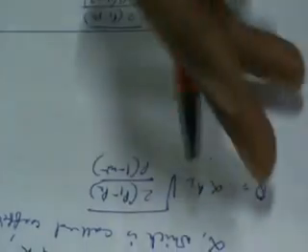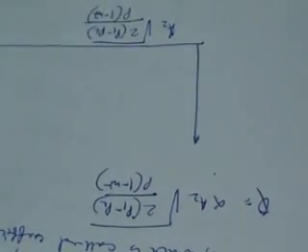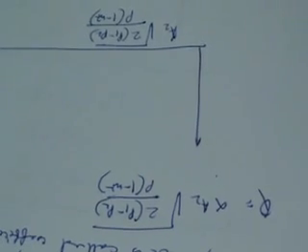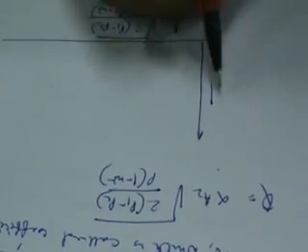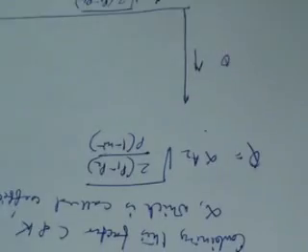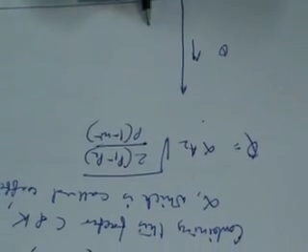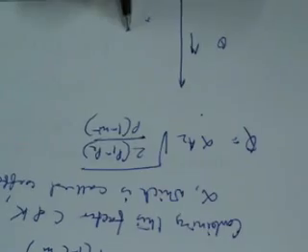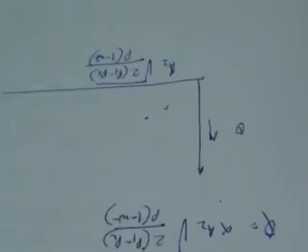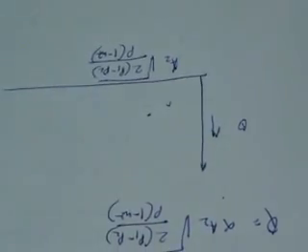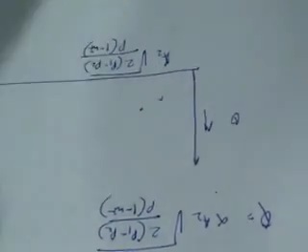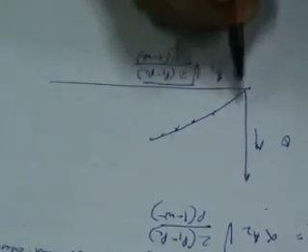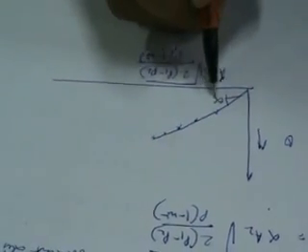And then if I somehow measure the quantity which is flowing through the duct, and plot Q versus this, if we change the pressure drop through a throttling device by changing the resistance and take a number of measurements, obviously the slope will give us the alpha value.